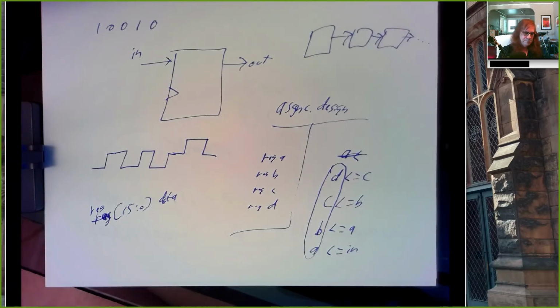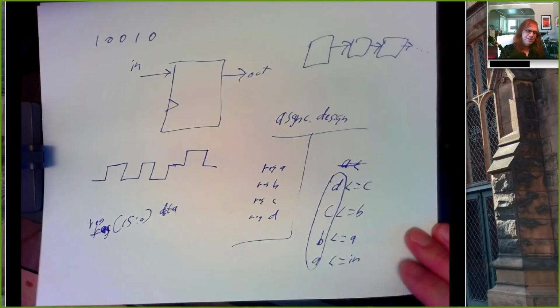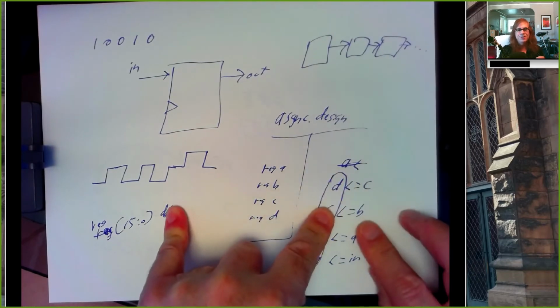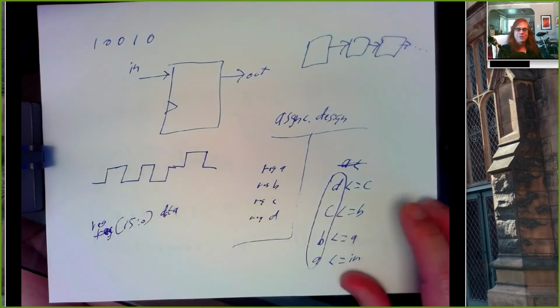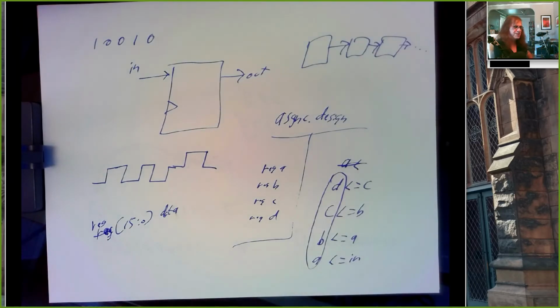Is it just because for loops are more complex? Is that why? Because you have to be careful whether you're asking a for loop to replicate your Verilog code or to actually create hardware that performs a for loop. And if you try to synthesize hardware that's actually doing a for loop and a counter and a check and so on, you end up with a very different piece of hardware in the end. But definitely experiment. This is the only way to learn this stuff. And if you want to get better with Verilog, definitely go ahead and dig into that.